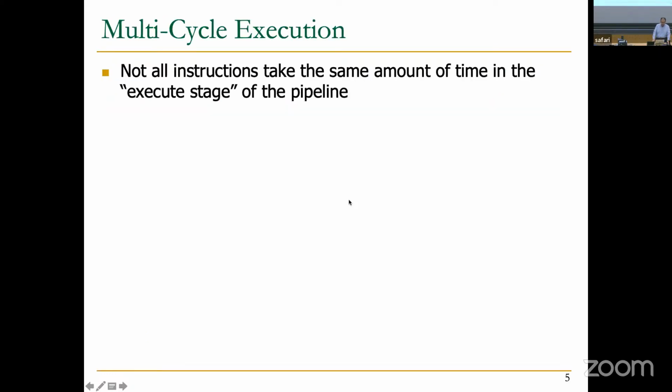What you have learned from microarchitecture is first the single cycle design, where we run each instruction in one whole cycle. And then we tried to do better and made a pipelined processor. We chunk the execution of an instruction into several stages in order to reduce the clock cycle time. But in reality, in most of today's architectures, we actually have multi-cycle execution.